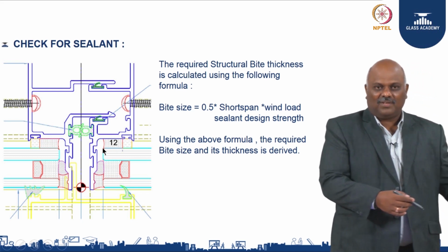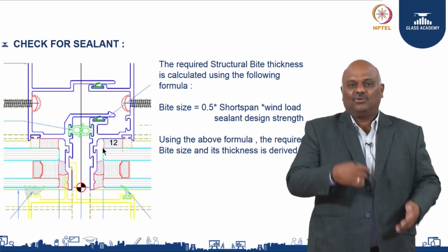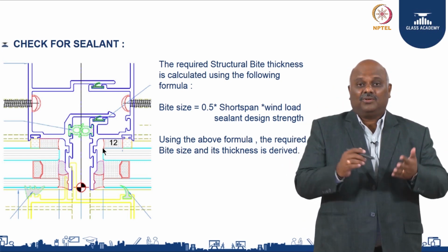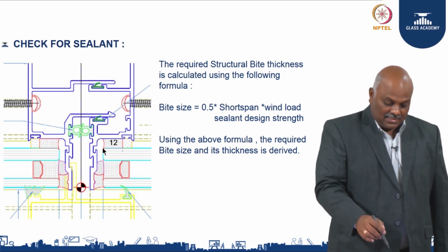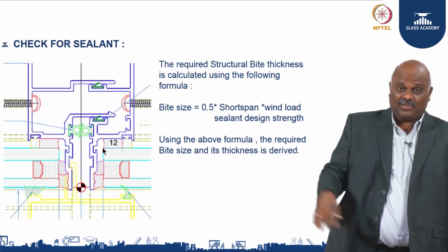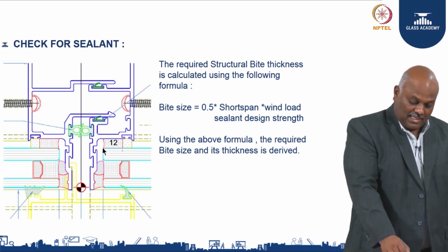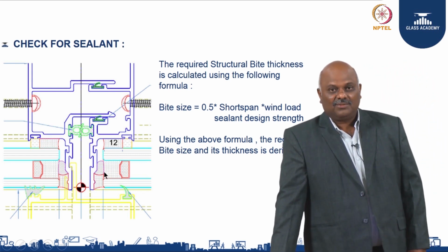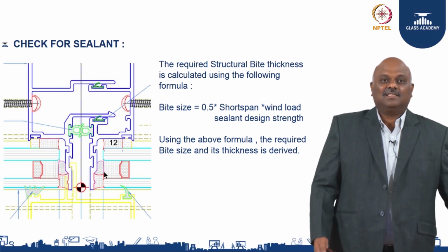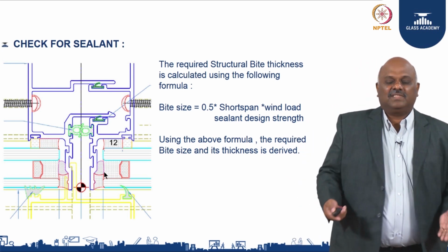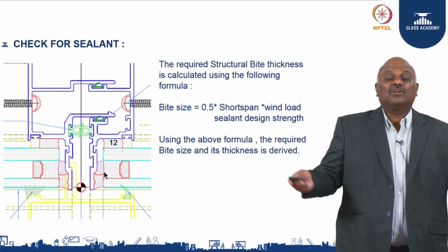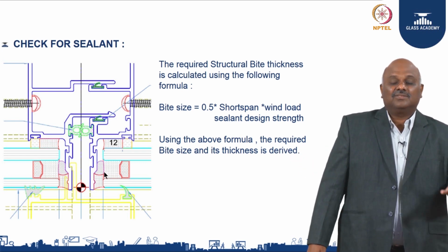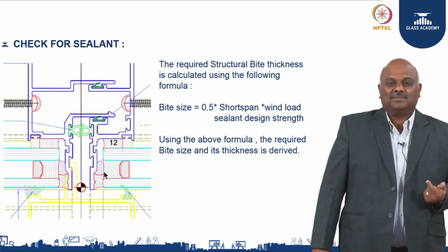So, you start from your substrate, do not do the reverse, where I have a mullion and then I have to fit the glass to it, no. You take the module, you talk about the glass, say there is a glass as your infill, take that infill and then design around it. Then only your system will start to work properly. For example, if I have a fixed mullion and then I want to fit something, it cannot work. Then you have to reduce your grid and do some combination to use your system. So, it is not advisable.